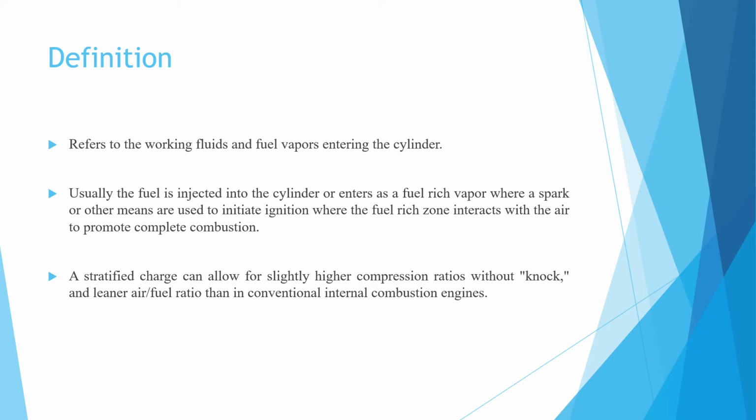Thus, the stratified charge engine is usually defined as an SI internal combustion engine in which the mixture in the zone of the spark plug is very much richer than that in the rest of the combustion chamber, that is, one which burns a lean overall fuel air mixture.